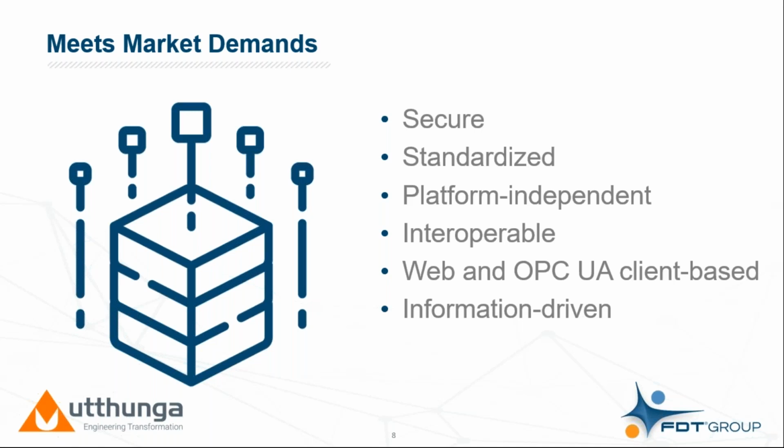Integration with things like higher level systems, asset management systems, production management systems, even up to an SAP level, to be able to get that information live off the factory floor without having to disturb the PLC or DCS environment to get access to that information. And it's a service-oriented architecture. We've got both web services available in the architecture as well as the OPC UA capabilities that make it a very flexible model to be able to acquire information from across the enterprise.